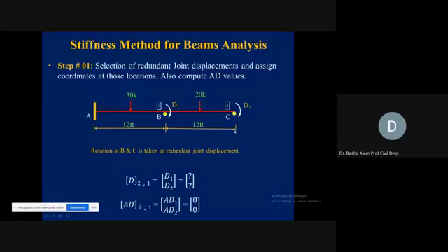And in problem 2 we will be taking, if corresponding to D2 we have some moment, how we include it. Or here I can give you the example. Let's say at B a moment was applied in the counterclockwise direction, let's say 10 kip feet. Counterclockwise means it was opposite to this D1, so negative sign because of that opposite sense, and you include minus 10 here at the AD1 location. At D2 we don't have anything, so that will still be 0. So now I hope you have noted down this sketch and all this, the 30 kip, 20 kip and those things.